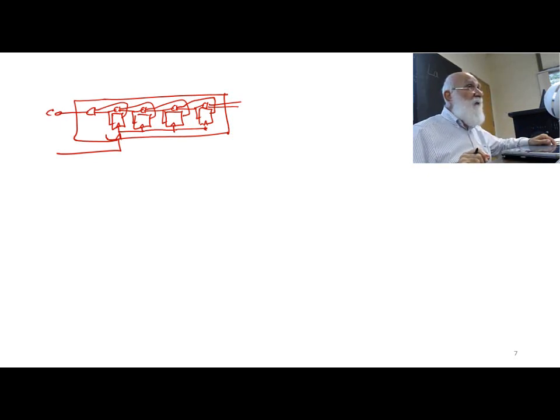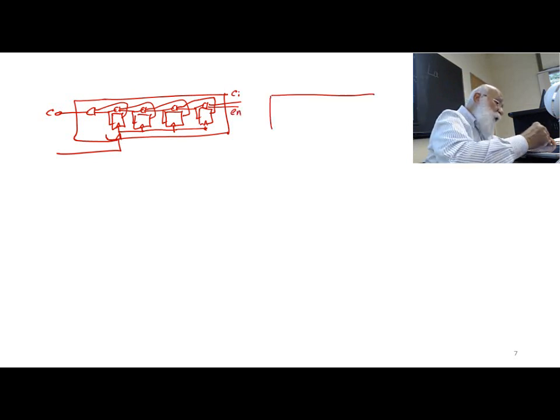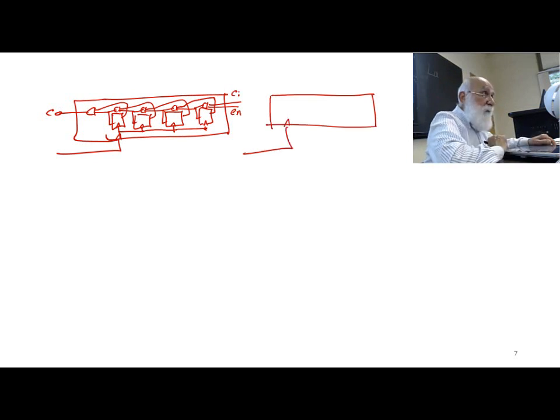Okay, this is a 4-bit counter, up counter. This I regarded as carry in, this I regarded as enable. If you decide that you want to take 2 of these and build an 8-bit counter, it has a carry in, it has an enable, it has a carry out. Connect the carry out of this to the carry in.